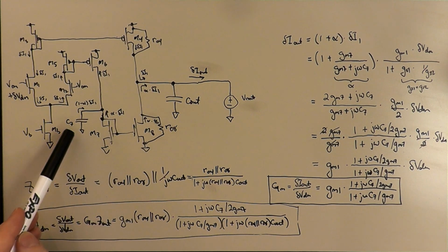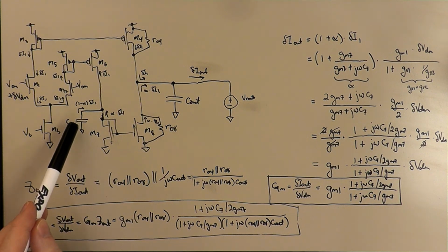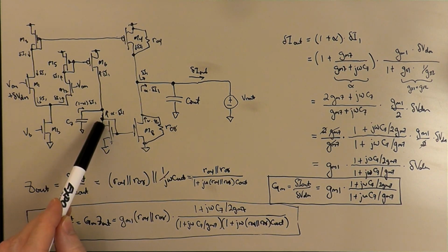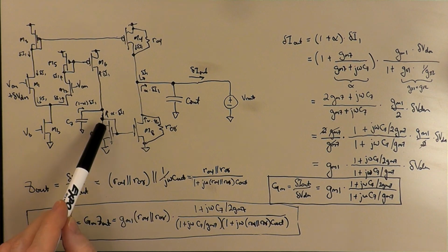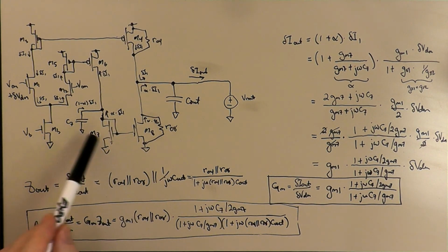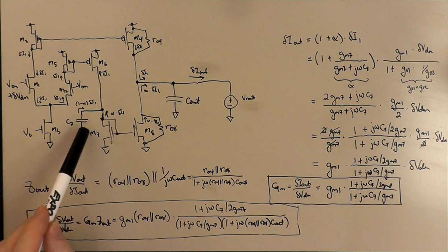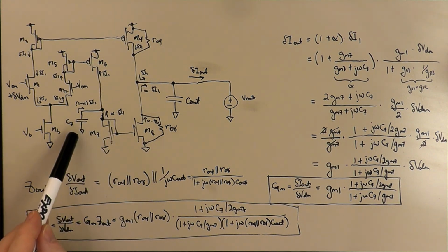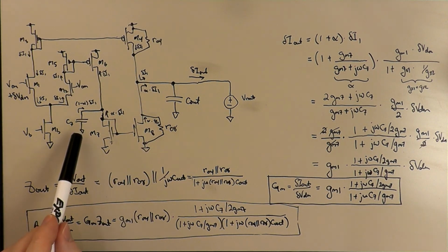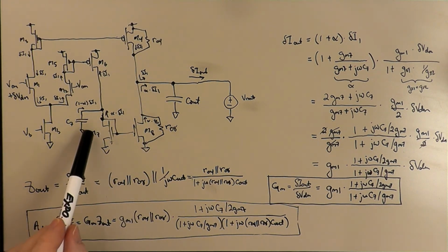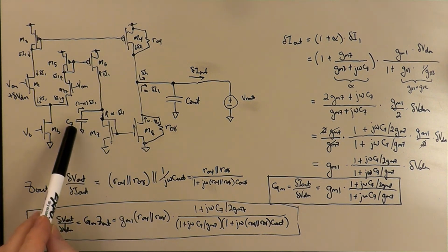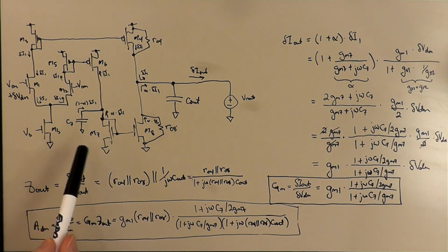Well, it's going to become significant at frequencies at which the impedance or admittance of the capacitor is comparable in magnitude to the conductance or the incremental resistance of the node that we're talking about. At frequencies above that crossover point, the capacitor will become more significant, and will steal most of the current away. And at frequencies below that, you can kind of think of the capacitor as not really mattering all that much to the calculation. You can leave it out.